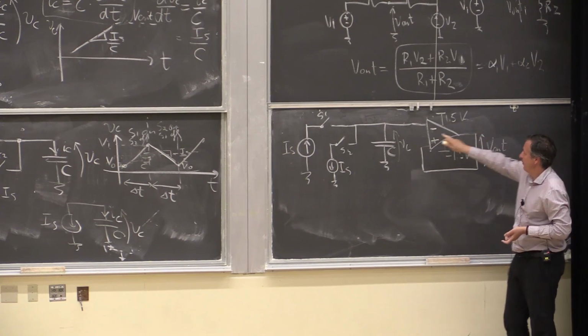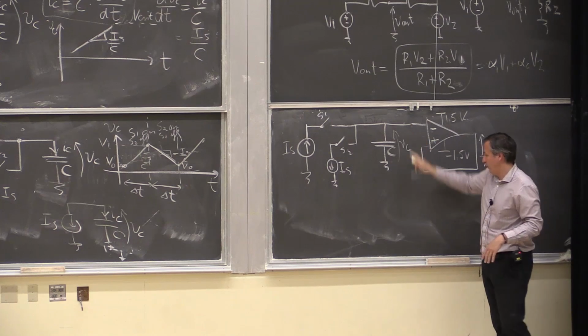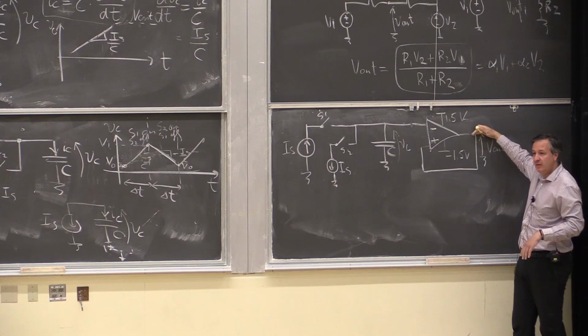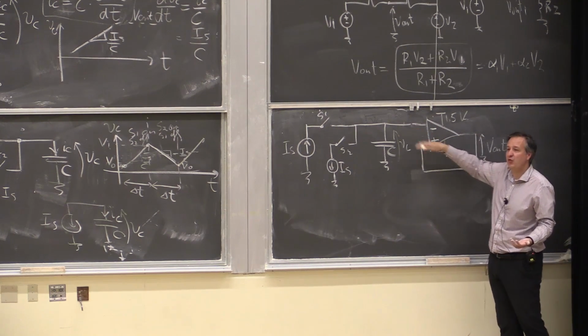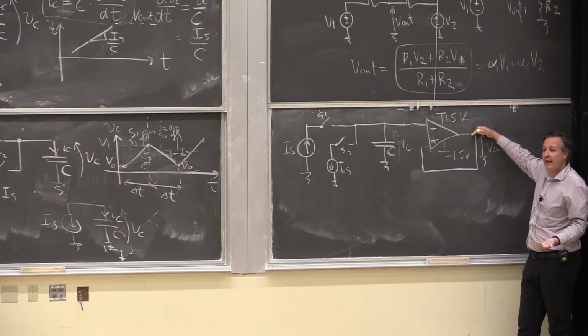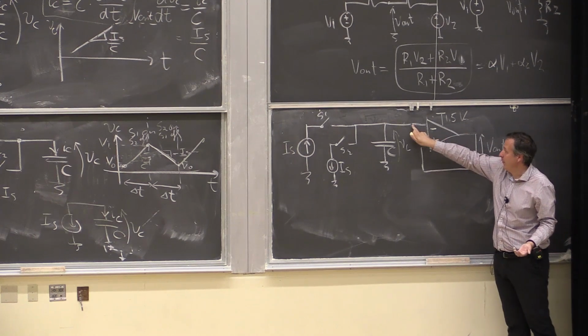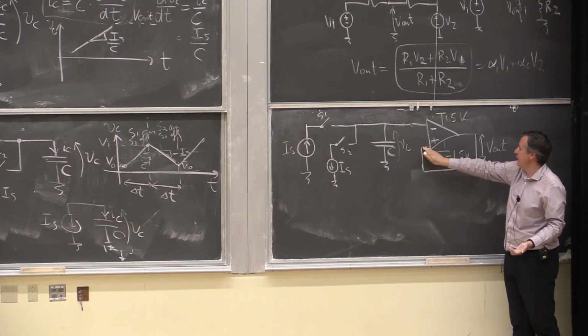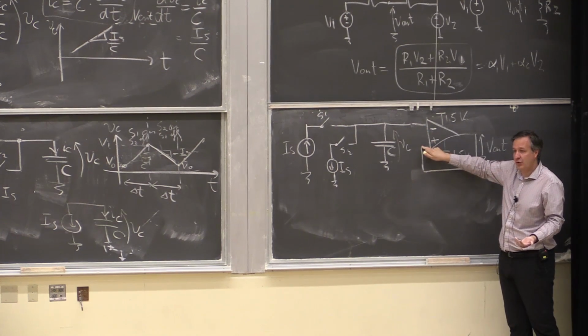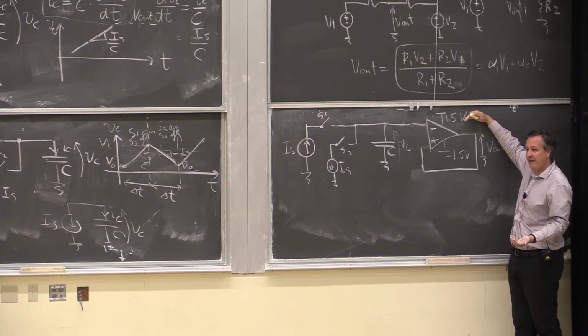So when this input is very, very low, then this output is going to be what? Regardless of that input. Now, let's say that input is minus 2 volts. This output will be 1.5, because minus 2 volts here, whether this is minus 1.5 or 1.5, if it's minus 1.5, still there's positive voltage developed here, so that should slam me into 1.5.